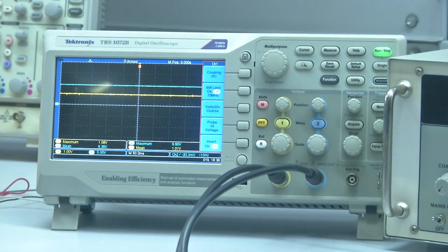With this we can understand that the selection of resistance in a non-inverting amplifier configuration is a little tricky, in the sense of the availability of resistors close to the required gain. However, since the input is directly connected to the positive terminal, the input impedance of the complete system is equal to the input impedance of the operational amplifier, which is very, very high. And we see that the gain is following our requirement, almost close to 10.